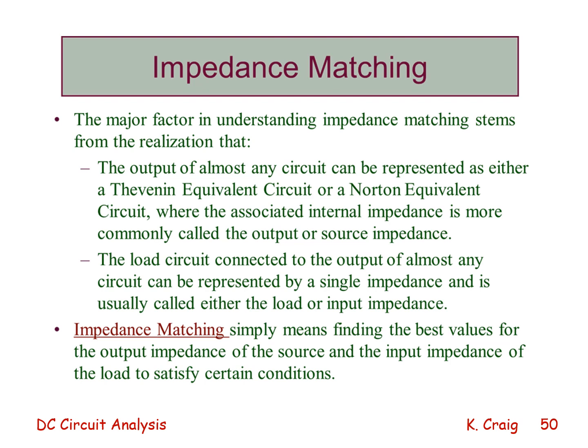Impedance matching. The major factor in understanding impedance matching stems from the realization that the output of almost any circuit can be represented as either a Thevenin equivalent circuit or a Norton equivalent circuit, where the associated internal impedance is more commonly called the output or source impedance.